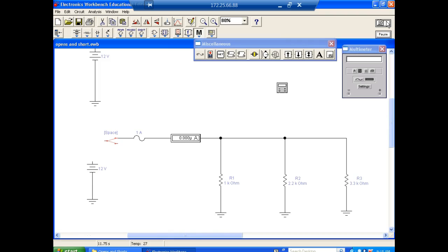So to get an open circuit, and this is why we put our fuses or our circuit breakers right here. We put them in series, right? You understand? It's not a series circuit, it's a parallel circuit. But when we connect something in series, it means we connect them in line. So if my fuse right here blows, it creates an open circuit. Any questions on that?